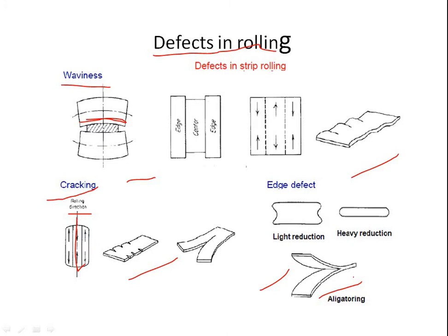Defects due to defective ingots. Internal defects like fissures in rolled products can occur due to incomplete welding of pipe and blowholes in the original ingot. Bad melting, low temperature pouring and uncontrolled solidification practices can cause inclusion defects and pearlite banding in steel products made from ingots. These defects can be minimized by use of good quality ingots. Okay, these are the defects.